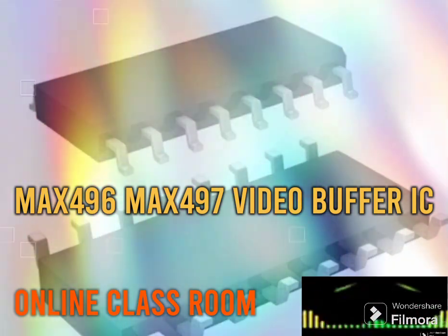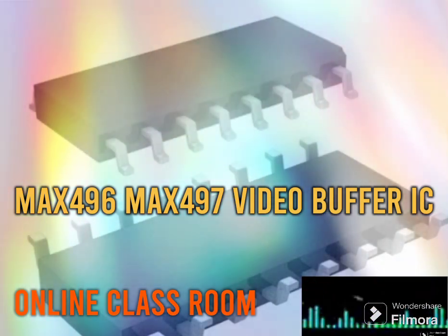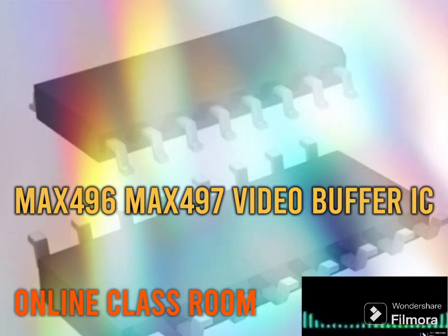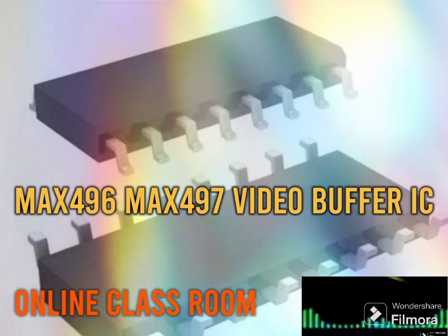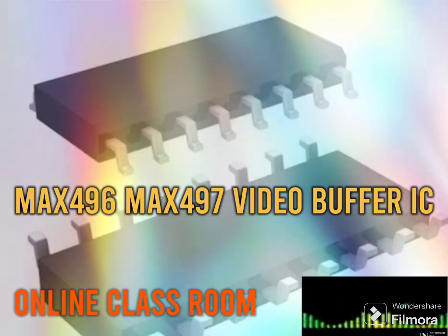It utilizes a unique two-stage architecture that combines the benefits of voltage feedback with the advantages of current mode feedback for high bandwidth and slew rate. These buffers are commonly used in applications such as computer workstations, surveillance, video, broadcast and high-definition TV systems, multimedia products, medical imaging and high-speed signal processing.